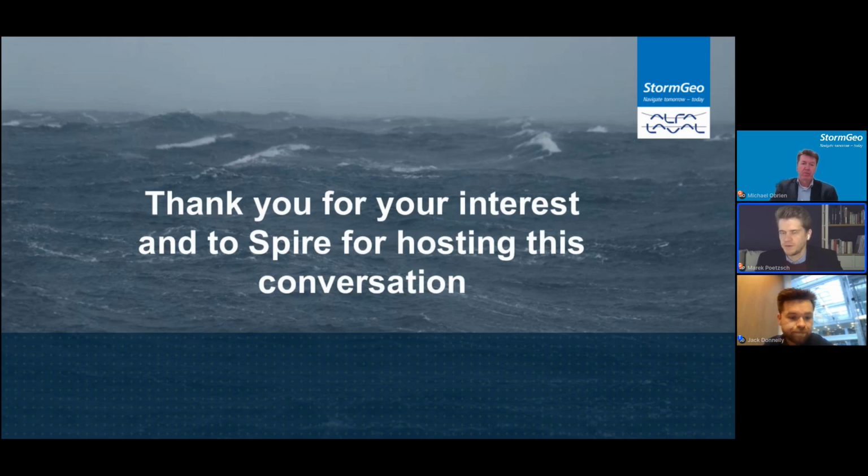Sure. One of the big impacts, as discussed before, is that the whole consumption of the entire year is taken and then divided by the distance and deadweight. Staying in port and receiving shore power will obviously reduce that consumption. Any consumption during port stay, where zero distance is made, which normally results in a really bad rating, would in this case be alleviated, because you don't make distance, but you also don't directly consume and emit CO2 from the ship, and that's the only one measured in CII.